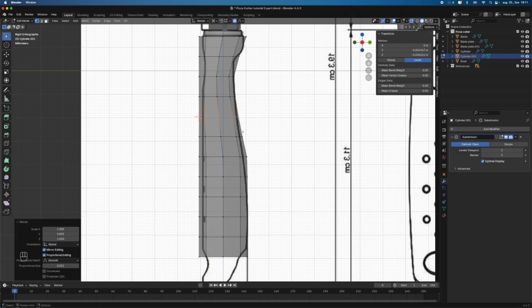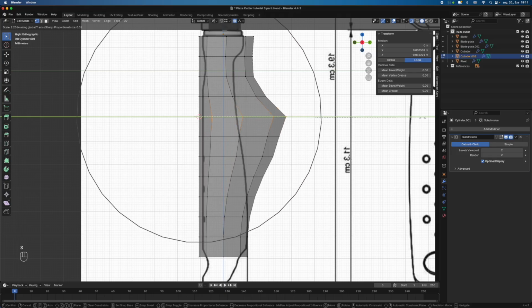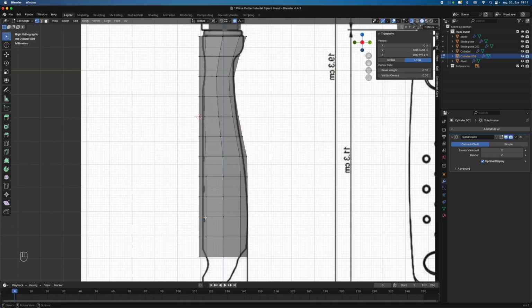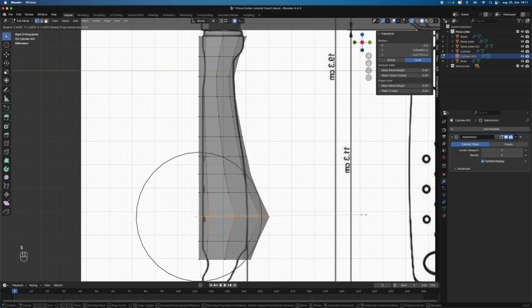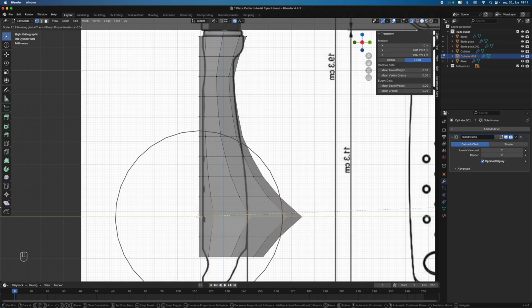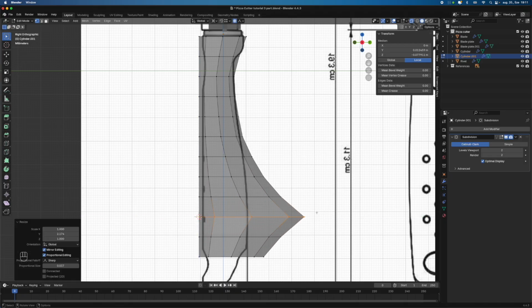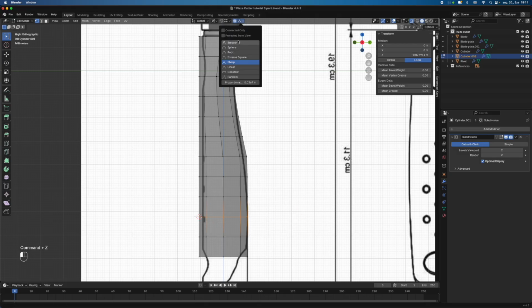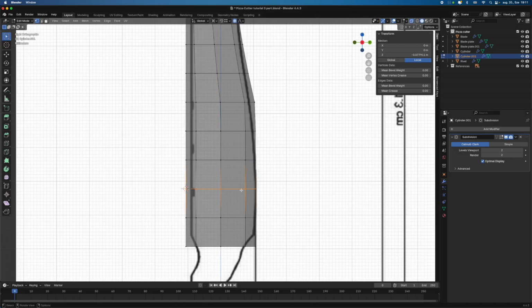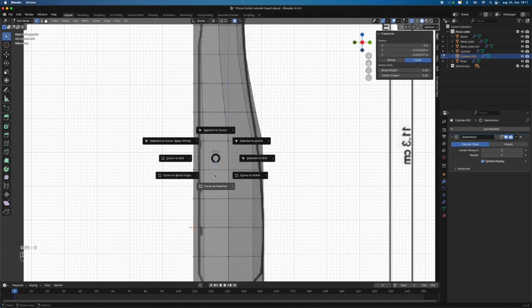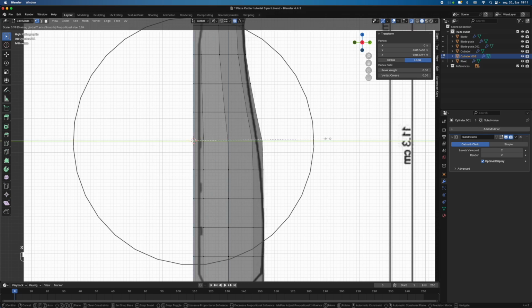However, anyways, if you don't like the falloff of this proportional editing, you can change it here. If you change it to sharp, it will look something like more sharp. Maybe it's more visible here. It isn't that smooth. It's more moved in this part. I want to change this back to smooth, but maybe this weird one would be okay for this, but I like it on smooth. Scale it.